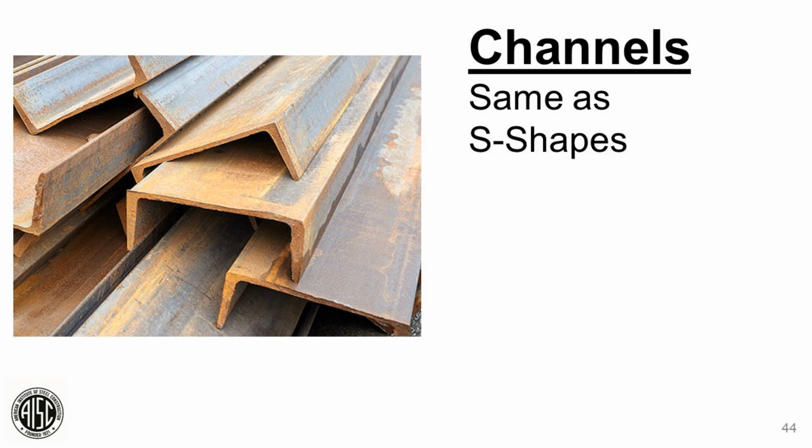Well, actually, if you read the article in Modern Steel Construction, it's going to state that, which is one of the reasons why I mentioned Modern Steel Construction as being a good source, because we have received updated information saying that A992 is the most common grade available for channels at this time. At the time when the Steel Construction Manual was published, that was not as prominently evident to us. It is now.